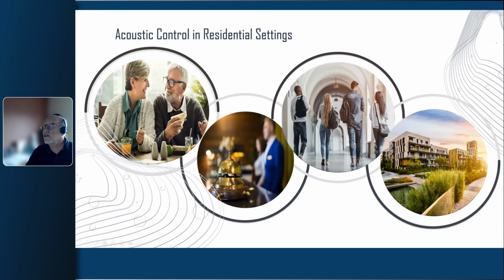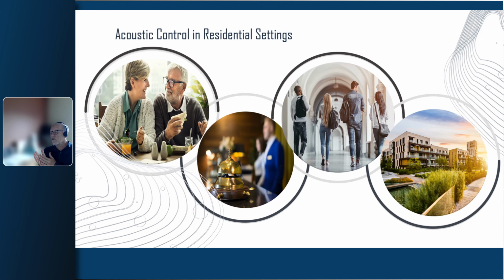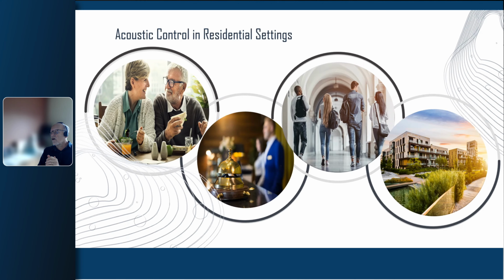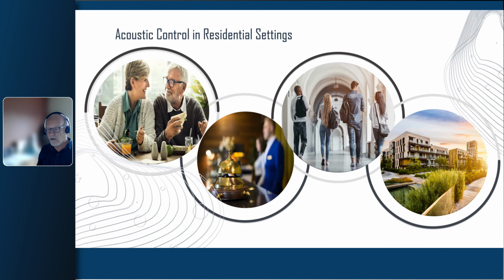We run into them in residential settings. I think all of us have been, or perhaps still are, in buildings where we want to maintain quiet and we don't want people running down hallways and hearing noise in the middle of the night. We run into that in hotels, of course, and in residential settings as well. Not as high a rating, not an STC 50. In some jurisdictions, I know in New York City, for example, the requirement for all new apartment buildings is STC 35. And LEED requirements in schools are at a minimum of STC 40.